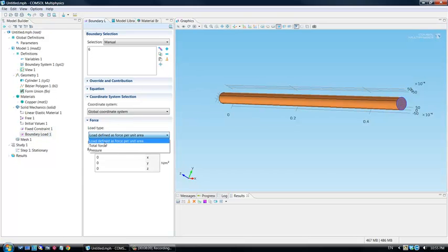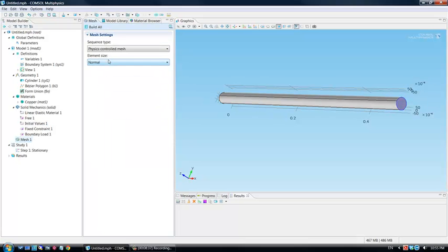Now the force, you can add a stress, a pressure, or total force, whichever you want, but I'll be adding it in units of force. So I've already predefined my force to be boundary force, or BC force, and I already defined it to be in the negative z direction.